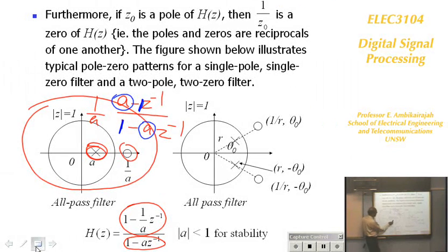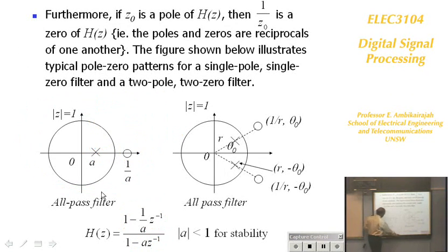Well, have a look here. In this case, there is one pole, which must be inside the unit circle. You reflect the pole's position to the outside and replace it by a zero. So when you do that, here's this one and that's our one. Find out the magnitude response of that.